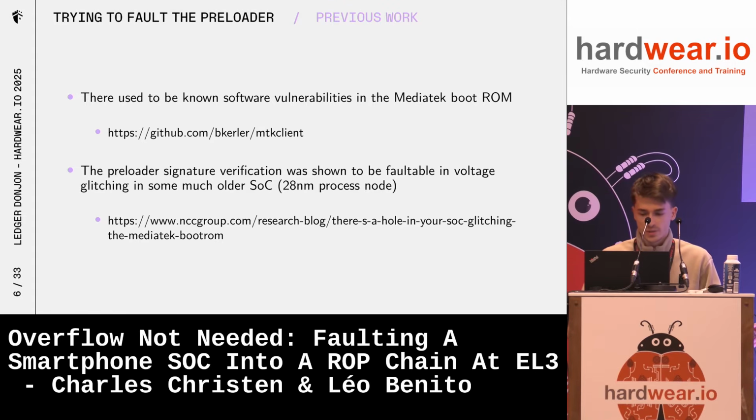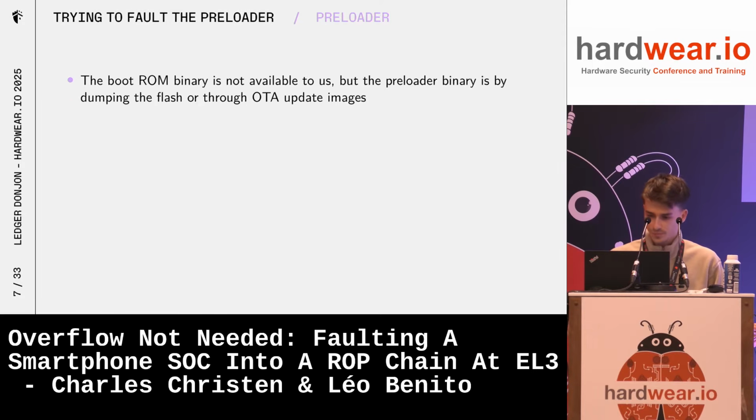Also, there has been some research faulting MediaTek SOCs. NCC Group glitched the preloader signature verification in the boot ROM in order to load a tampered preloader. They did that on a 28nm process node, so on a chip built with that technology. But it's far from today's technology, so we wanted to know whether it was possible today.